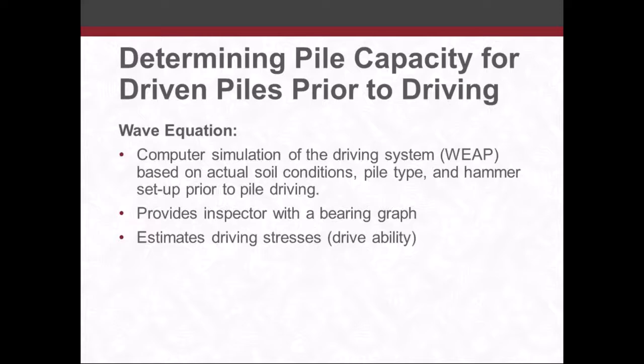The wave equation doesn't determine how deep a pile is going to be driven to achieve a capacity. That needs to be tested in the field. But what it does determine is the blow count versus capacity, as well as the stresses for the hammer and pile setup.